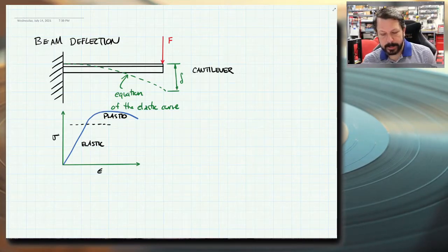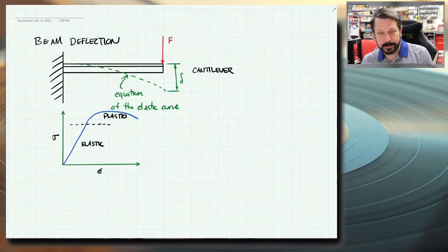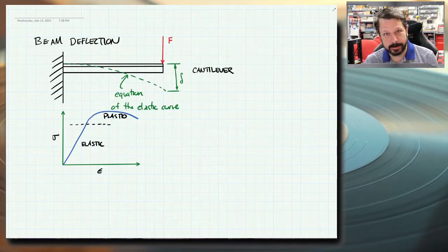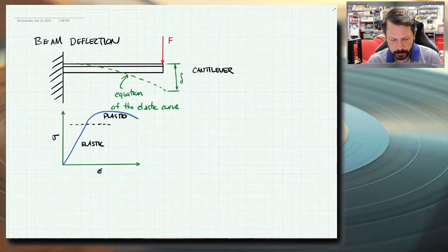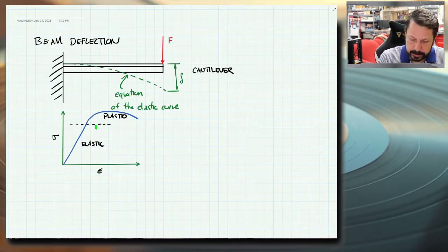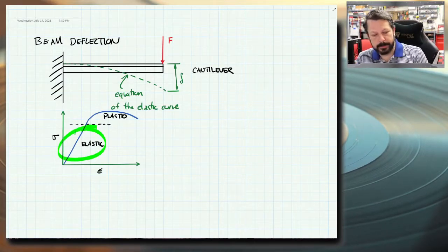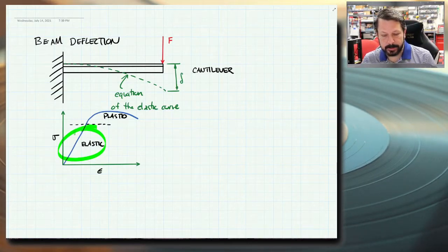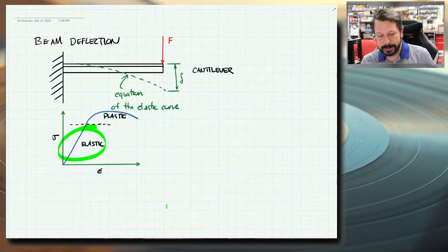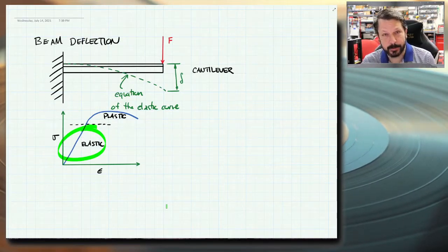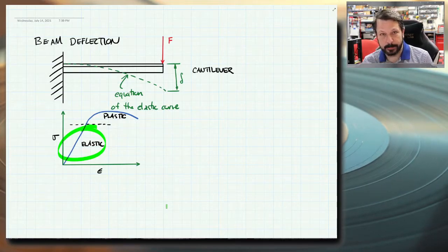So this would be a very ductile type material. Normally this elastic region, the linear region, is much more vertical. I've just exaggerated it so that we could see it versus it being almost a vertical line. So we're operating down in this region here with our beams. If we get into that plastic region, then we have gone to some place where this beam does not need to operate, and this equation would not model it correctly anyway. It's going to have some kind of permanent deformation.